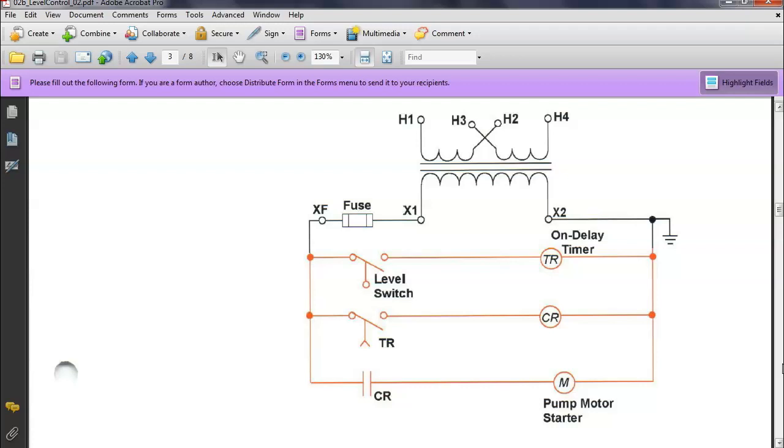So this is going to compensate for the liquid sloshing up at the top while we're trying to move past the sensor. Because when liquids are in motion, they have a tendency to slosh. What would happen if you stopped it? It comes up and hits it, and then you get a slosh, it drops down, and your relay would come in. So it would vibrate for a while. So all we're doing is just adding a little time, right? The sensor goes true, brings in the timer. The timer lets it fill up above the switch, and now it's sloshing up above that, and it's not going to cause any problems, right? So that's what this is.